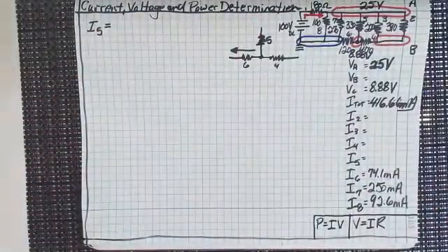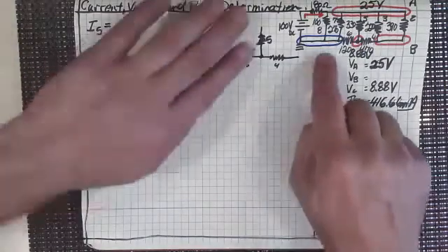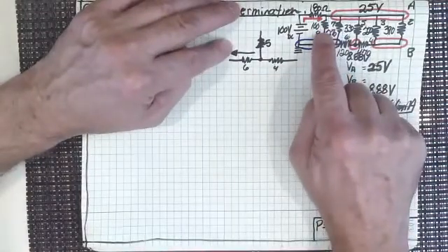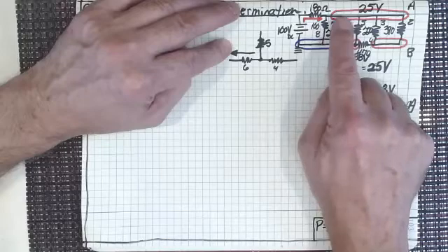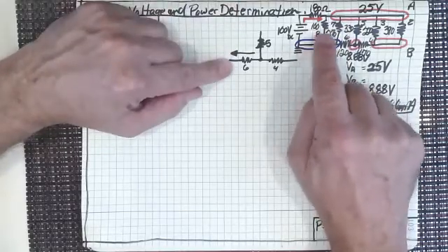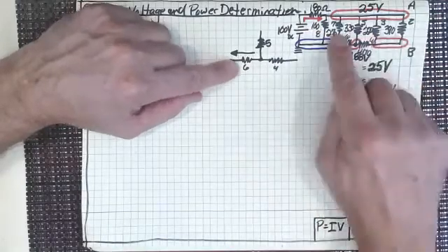Now, that's a node, but it's sort of a boring node because it's 0 volts. But current was flowing back into that node through those two resistors, the 100 and the 270 ohm resistor. The only thing that was stopping it from short circuiting out were those two resistor values, right? So they've come back.